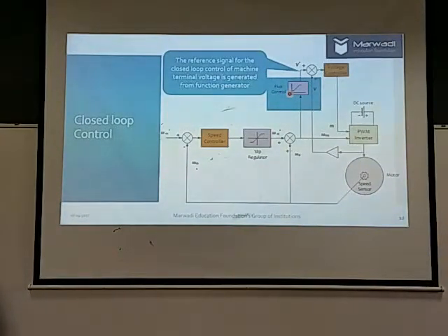So voltage will be maintained and frequency will increase, and that will result in the field weakening. Now this voltage, which is determined from the flux control mechanism, is given to this, and the actual voltage can be sensed, and then the voltage controller will take care of the actual modulation index, and modulation index is given to the PWM inverter. We can adopt any PWM technique such as sine PWM or SVPWM or any other technique to ensure that the modulation index is achieved.